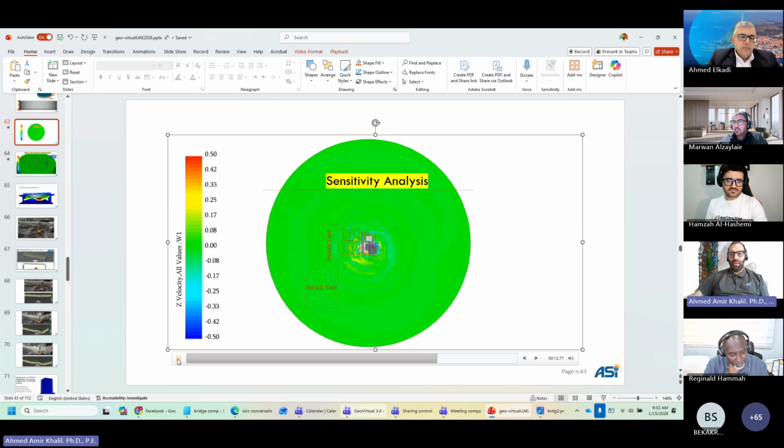But also we found that the experience from the impact and the vibration monitoring at one site is transferable to other sites which have somewhat similar characteristics. We're able to have more confidence every time we predict the vibrations, and we've had cases where the structures are very close by and we're able to get good estimates for vibration.